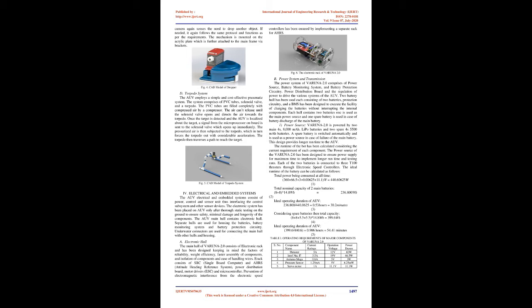A servo motor is specifically used as it can be precisely controlled for inputs in terms of angular values it has to rotate. The columns are located both in clockwise and counterclockwise directions with respect to the mean position of the servo arm. The arm makes the plate rotate until the circular cutout in the plate coincides with the column profile.